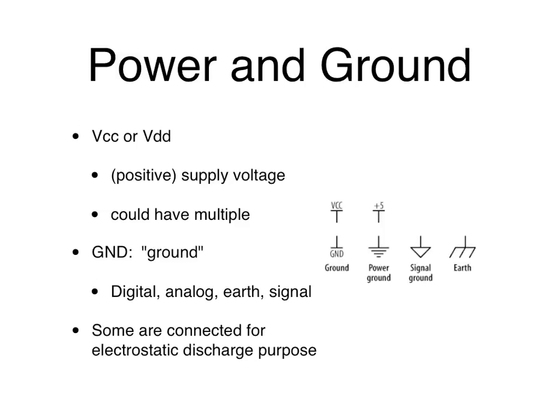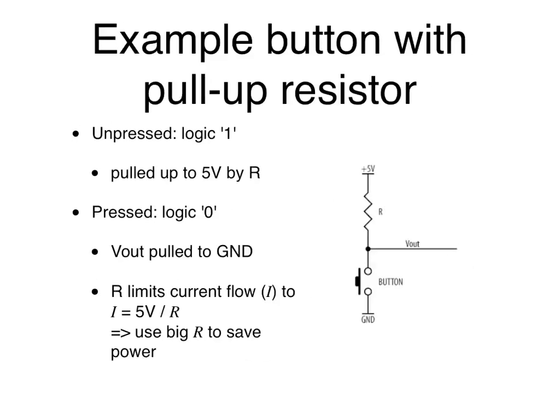Yeah, I think you still want to be careful, so that's why there are different kinds of ground there. Okay, and another thing you might want to know is this concept of a pull-up. So what's a pull-up? A pull-up is basically a resistor that's tied to, a lot of times, the supply level. It could be like 5 volts, and sometimes that's VCC or VDD.